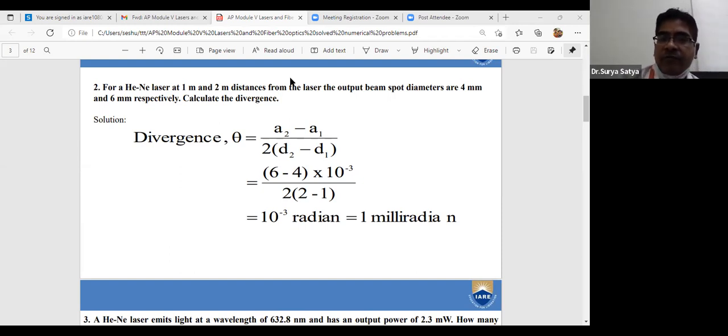Cladding. Whereas in gradient index fiber, the refractive index is not a constant, but it smoothly varies and decreases as we go away from the axis. So that is what we call gradient index fiber. And depending upon the number of modes possible, that is the number of paths available for the light to propagate in the fiber, it is divided into two types: one is single mode and the other is multi mode.